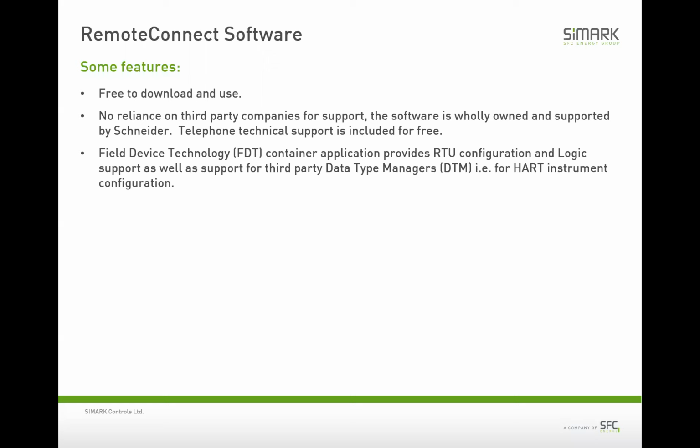The software is using a current technology called field device technology, FDT, where you have FDT containers, or a container, which is Remote Connect, and then the device type managers, or DTMs, are put into the container and used to connect to the RTU and do the configuration. So here you can add in extra DTMs, such as the HART instrument DTM, into the Remote Connect container and utilize that with the HART pass-through for the instrumentation as well.